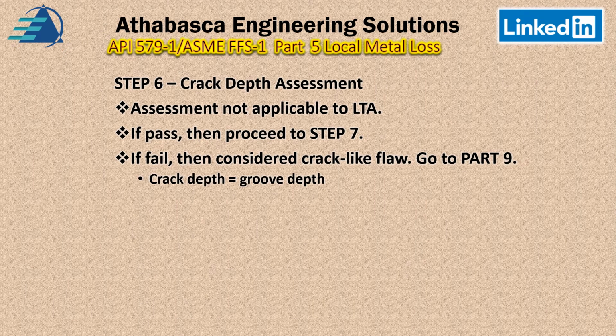So in this case, our crack depth should be approximately equal to the groove depth when we do the analysis, and the crack length is the groove length. So these are the criteria we would follow if we were to go to Part 9. We would have to do this little conversion factor before we would jump in.